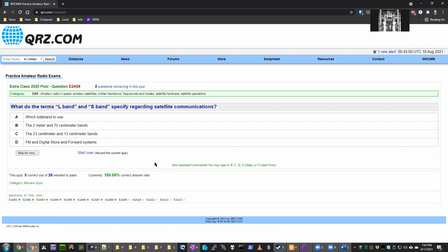No, and one of the reasons with FM that you do see the loudest guy wins is a thing we'll talk about a little bit later called capture effect. That's actually one of the reasons why aviation still uses AM. If it was using FM, you'd have to deal with capture effect, and that loudest transmitter is going to win out over other planes, and that could cause a safety issue.